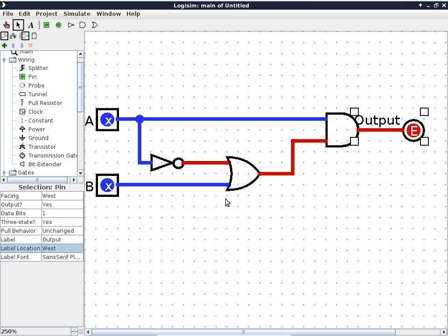Instead of using a NOT gate, could we just negate one of the inputs? Yes, you can. If you want to save a NOT gate, you can use the negation of an input pin of the NOR gate, and so the bubble will appear at the input, the top input pin over here, and it will still do the same thing of negating that particular input. So that works as well. Not a problem. All right.